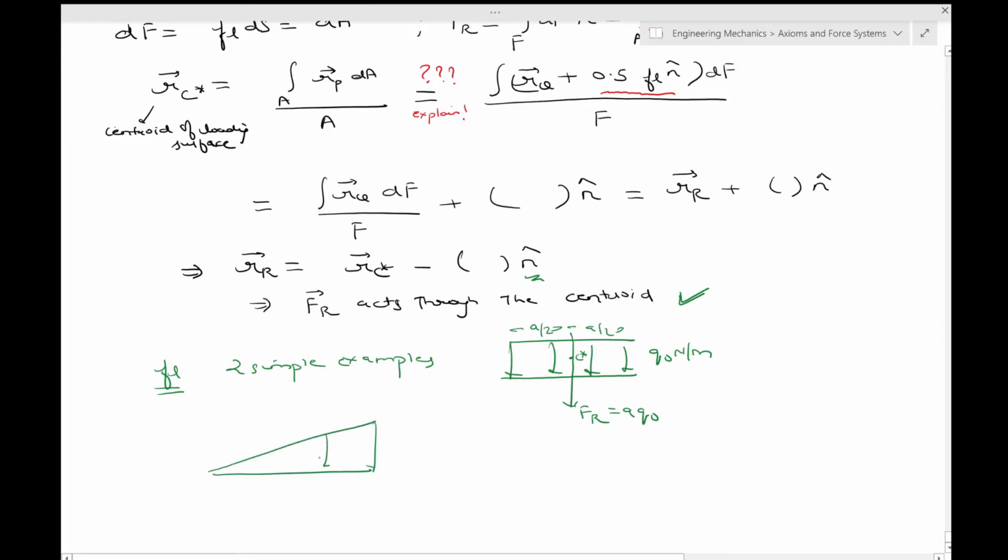distribution, okay, the resultant of this, so the maximum value is q naught Newton per meter. Okay, and the loading is actually increasing with the length. So this is very easily seeable. Say if you have a container of water, okay, and the loading over here will be the maximum because the pressure on this particular face will be maximum, and as you go up it will keep on decreasing. Okay, so this is a similar sort of behavior, a triangular load so called.